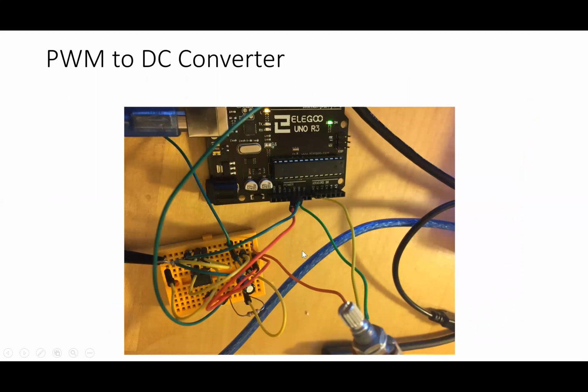So here's the circuit. This is my potentiometer plugged into pin A0 here. You'll see the chip here. Notice that there's a cut-out on this breadboard. This means the pins are not connected across here. So just as in the fritzing layout you saw on the last slide, you can connect to pins along here and along here. And that's what we've done. And here's the capacitor and here's that resistor. So let's take a look at what we get.